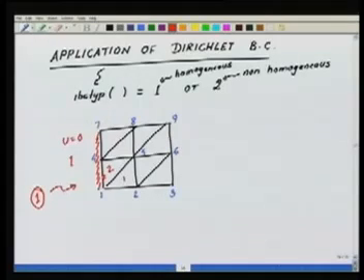To make the list of the degrees of freedom lying on the boundary, I go to the particular edge, which is the second edge of the element, and I ask which are the degrees of freedom which are non-zero, active on this edge. I find that for this edge, the local degree of freedom 2 and the local 3. So if I draw the second element, this is local 1, local 2, local 3. These are the ones which are lying on this edge. So these are the ones which have to be fixed.